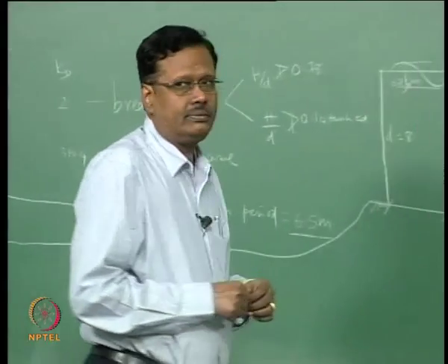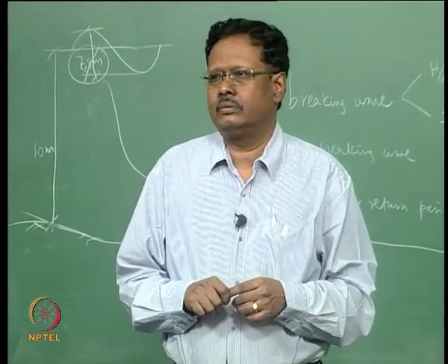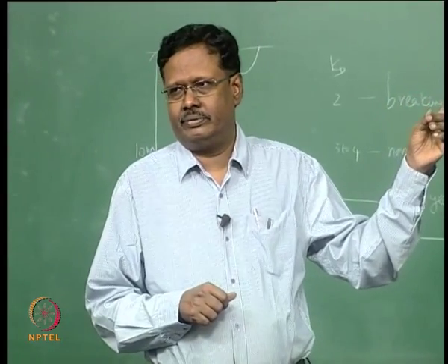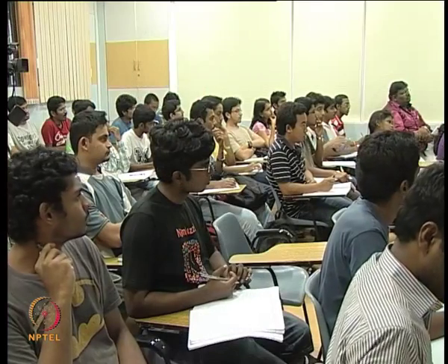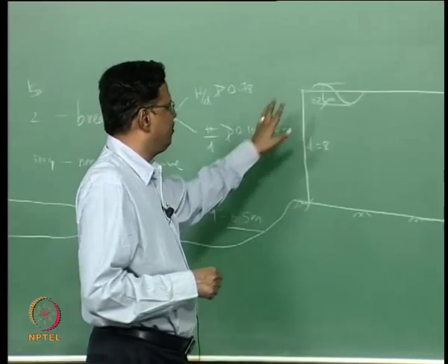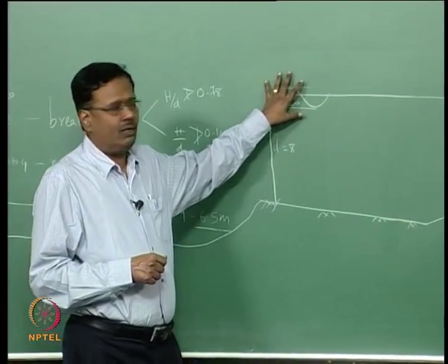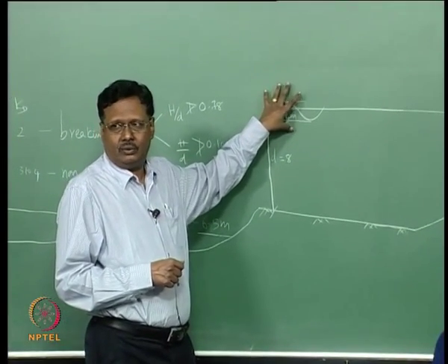The design wave at 5 meter depth is 3.9 meters, because that is a breaking wave. Yes, a 6.5 meter wave comes, it will break at this location. A 4 meter wave when it comes here will not break.